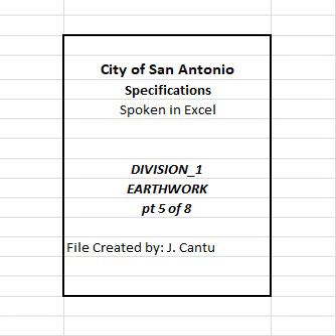2. Gradation tolerances. When gradation requirements are shown on the plans, material is acceptable when not more than one of the 5 most recent gradation tests is outside the specified limits on any individual sieve by more than 5 percentage points. 3. Density tolerances. Compaction work is acceptable when not more than one of the 5 most recent density tests is outside the specified density limits, and no test is outside the limits by more than 3 pounds per cubic foot. 4. Plasticity tolerances. Material is acceptable when not more than one of the 5 most recent PI tests is outside the specified limit by no more than 2 points.